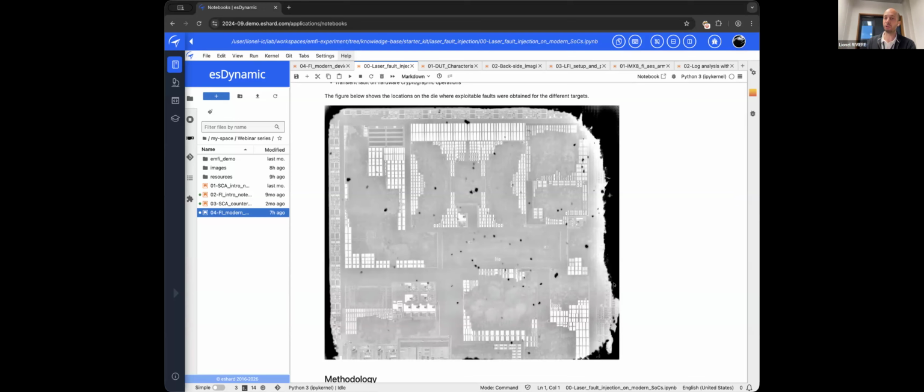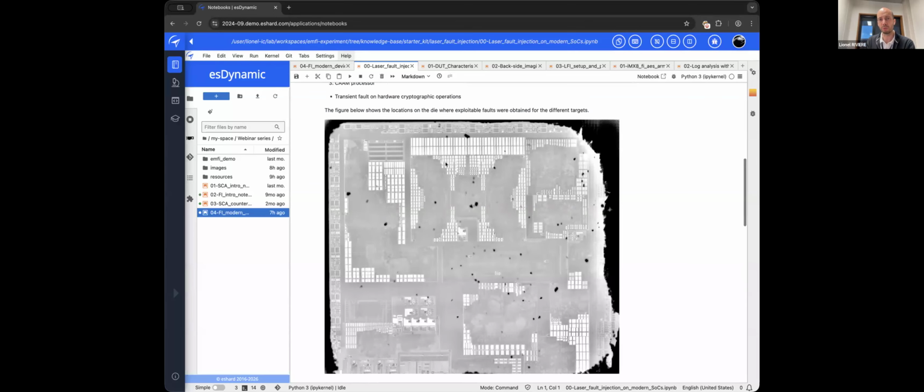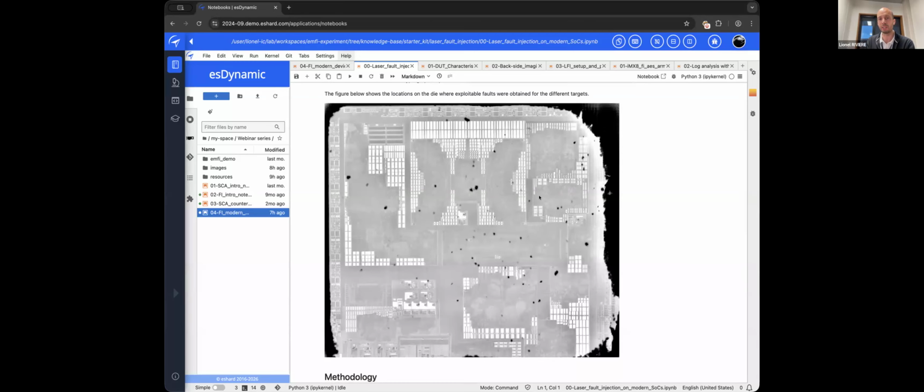Of course, as I'm going to do laser, my DUT needs to be prepared. So that could also be a first challenge. In some cases, it's not even possible. You also need the flip chip so that the silicon is directly visible to the IR camera, but also for the laser faults, the laser beam, basically. So once we have that, we cannot grasp basically if it's big or not, but once we have that, we will need to state, okay, where do I start?